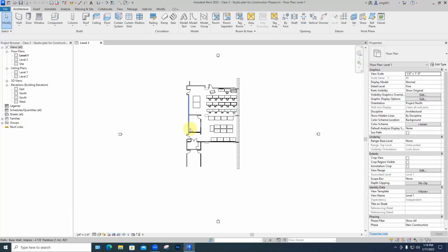It will often happen that when you get a Revit model of an existing building, it will already have maybe several different phases in it. At that point, you need to ask whoever is giving it to you, if there's already 3 phases in there of previous work, do you want to consider this phase 4? Or can I just start again with assuming all this is existing conditions, and then we're going to do new construction as essentially our phase 2?